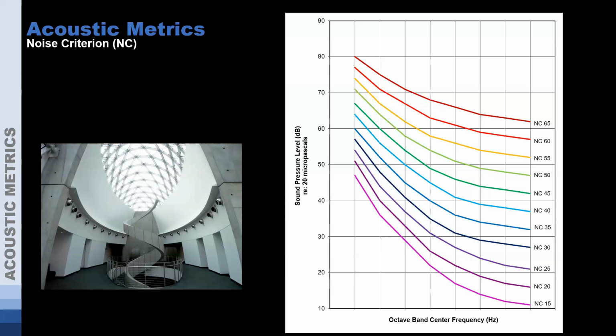If it's really large seating capacity and you've got a lot of speech amplification, that might move up a little bit closer to NC 50. But again, those NC 45, NC 50 spaces are loud background sound levels. You don't want that in your classroom space, or to be trying to sleep in a space like that at your house or in a hotel. So it's just another way that acoustic consultants can look at how the sound is impacting people within a building.